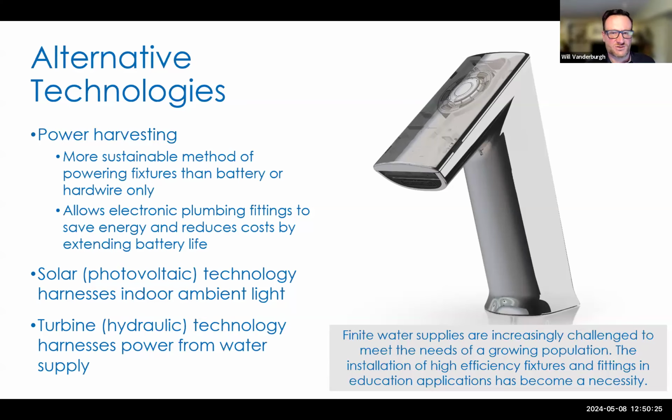And that's where something like solar comes in. Solar technology now has no moving parts in the water stream and is able to generate power based off of the lighting that's in the room. And it will even function happily on LED lighting and occupancy lighting. It takes about 90 seconds for that capacitor inside the head to charge the faucet to activate, which is typically plenty of time for a user to come into the washroom and activate that.